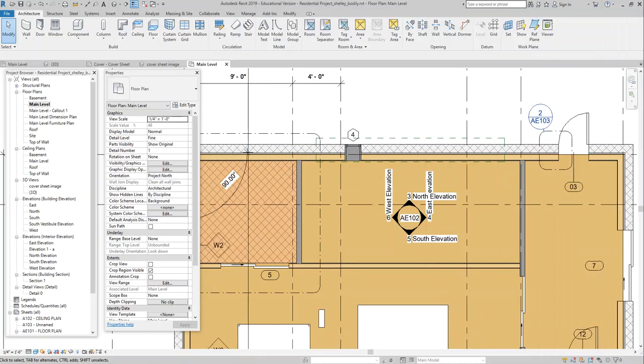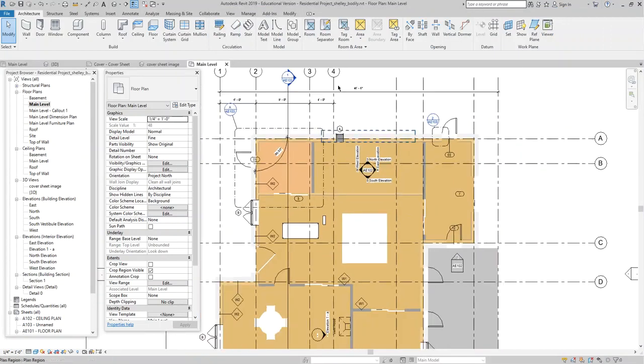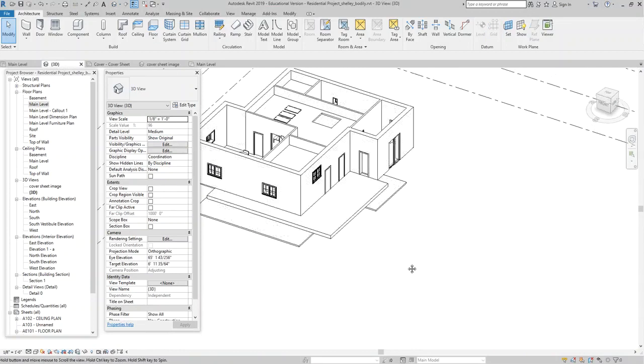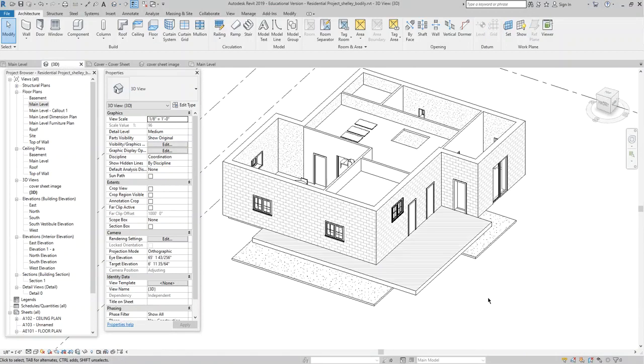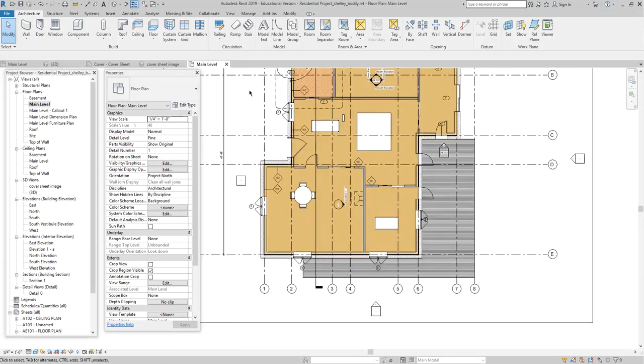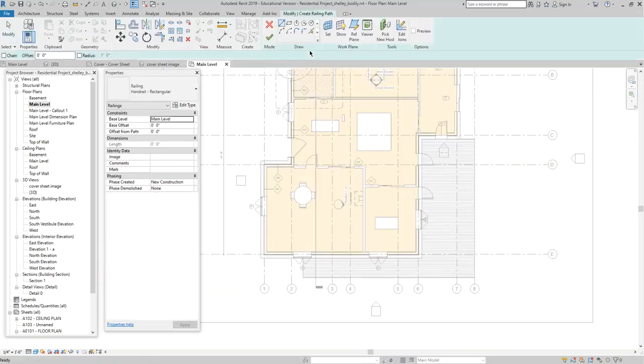To create a railing, we'll jump ahead just a tiny bit because we can, right? To create a railing, which we'll learn a little bit more about when we create stairs, let me show you how to create a railing around this. I'm going to go into my main level again. Okay, and you're going to notice on the architecture tab here under build, we have a railing option. All right, so I can drop down and I can choose sketch path. And again, I bump into sketch mode.